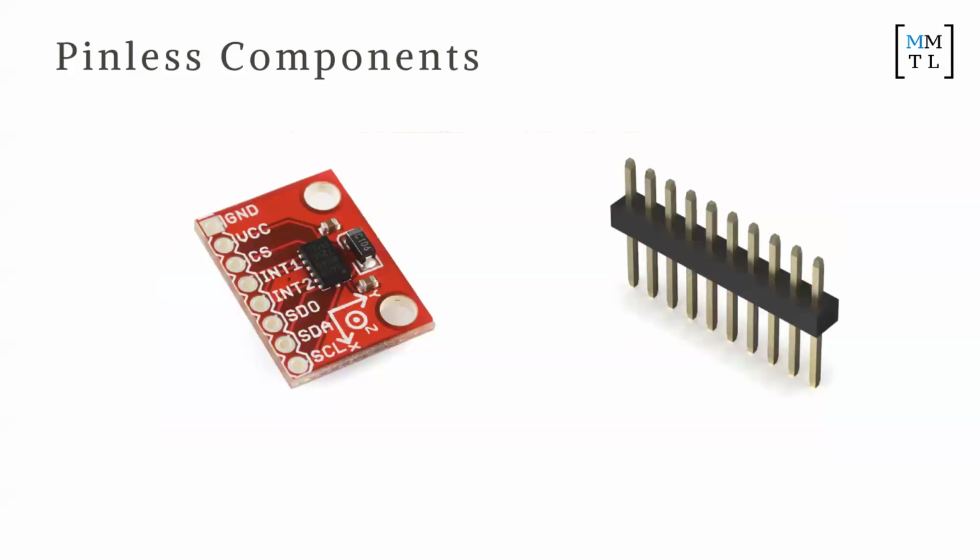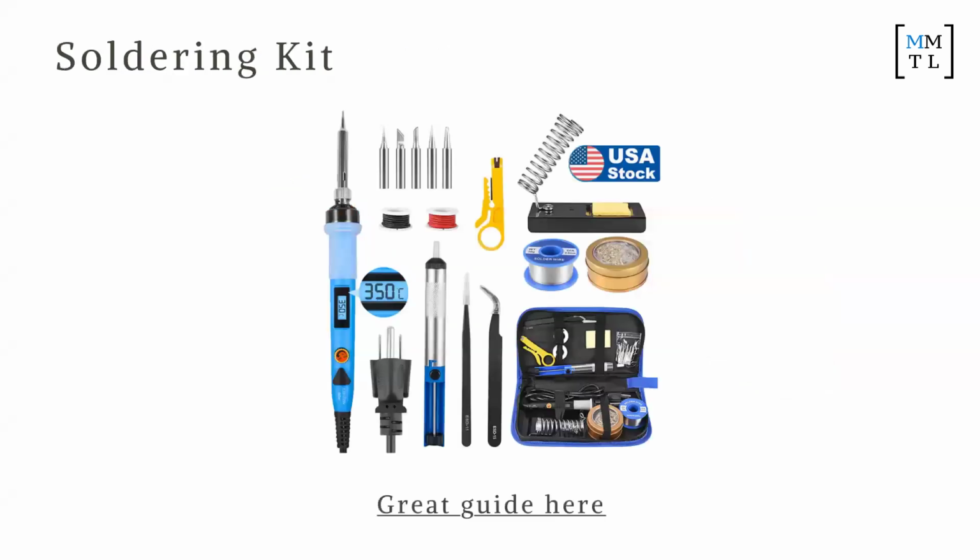All right, now why do we need solder? Sometimes you get what's called pinless components. We've made sure that every component in this pack is pinned, meaning that there are pins that have already been pre-soldered for you, so you don't have to deal with soldering. But sometimes you might see components out in the wild that don't have any pins whatsoever. In that case, you must buy this pin header here, and then you have to solder this component to this component here. You literally just put this above like that, and then you solder the components. That's how you electrically connect these components.